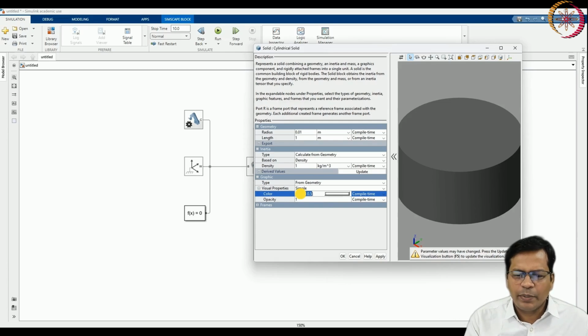Okay, so based on the volume it will create the mass. If its mass is evenly distributed, it automatically comes at the centroid of that geometry. Okay, color, so as to distinguish between different links, I have put it as 0.800. That means it is 0 to 1 scale for R, for G and B. If it is 0.800, 8 for R and 0 for green and blue components. So it becomes almost like red. Okay.